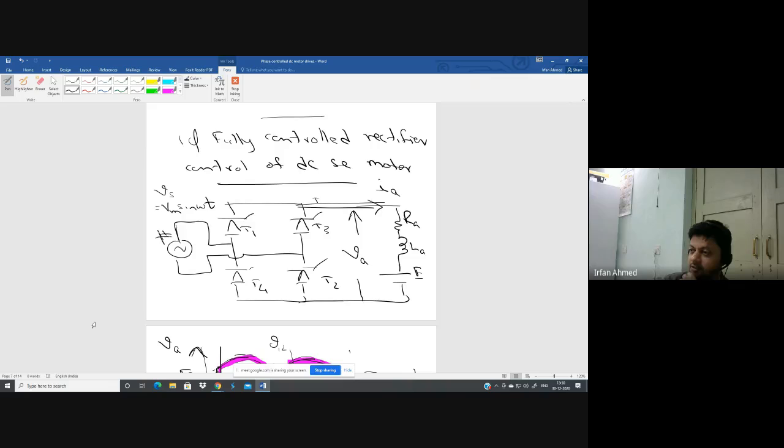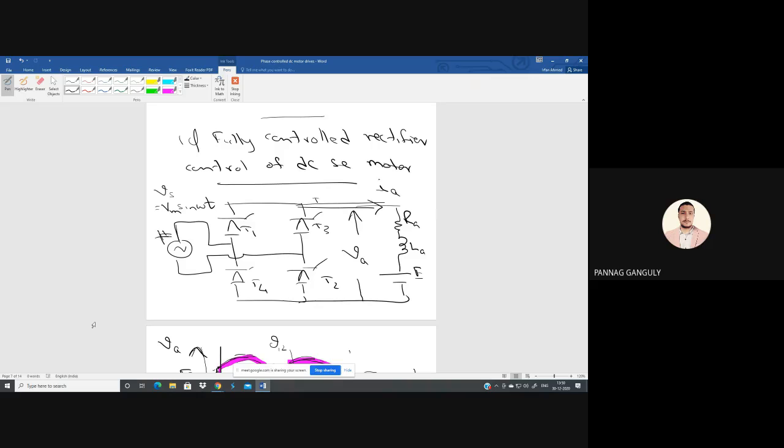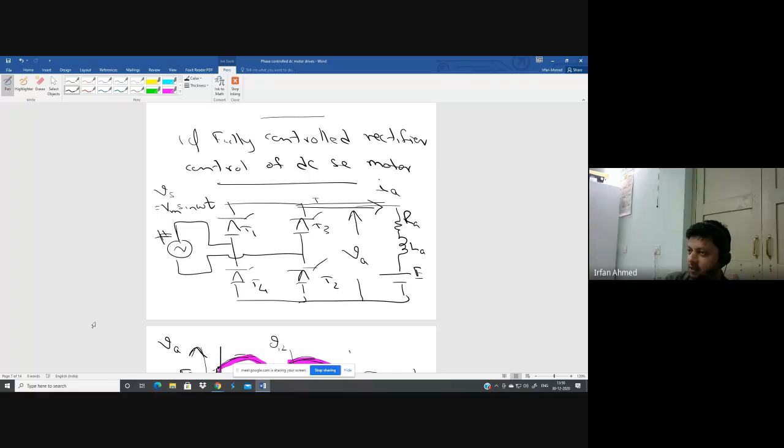For that you are using an induction motor. If you have to control the speed of induction motor also, then it is a very foolish method, you can say. That induction motor is run at constant speed and it drives the generator at constant speed. So how do you change the voltage of the generator? So generator field control. Yes, by changing the field current of the generator, you control the generator voltage, and that generator voltage is fed to the motor whose speed is to be controlled. Okay, so that was the Ward-Leonard method.